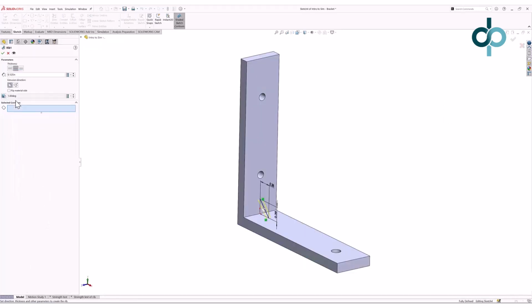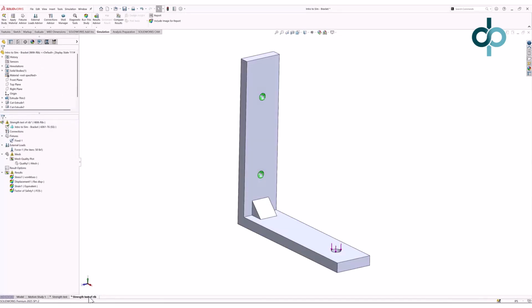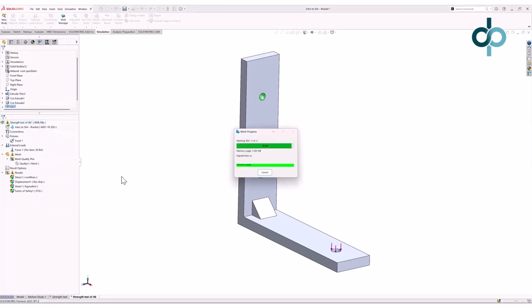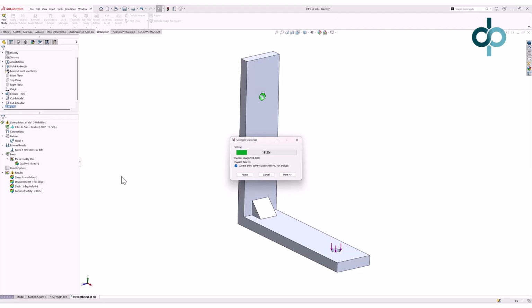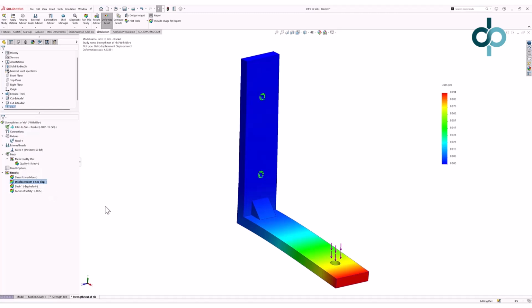So here we are in the CAD model. I can edit the feature. I can change the size here. It's 1/8 of an inch. Let's change that, double it. No, 4 times that. Let's make it 1/2 an inch and let's see if that makes an impact. Again, let's look at the displacement and see what happens here. And now we're below that 0.1 inches mark. Better. That's not a huge difference.